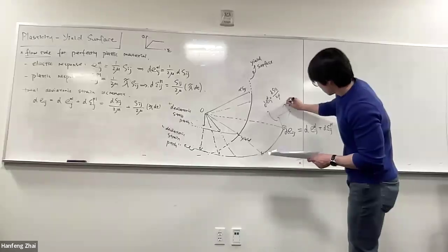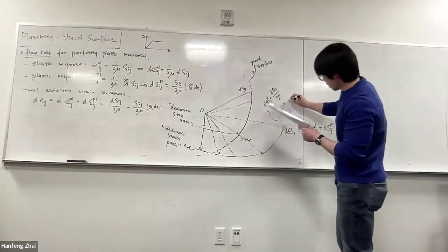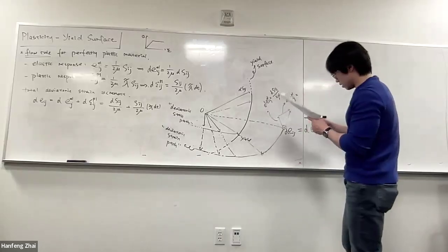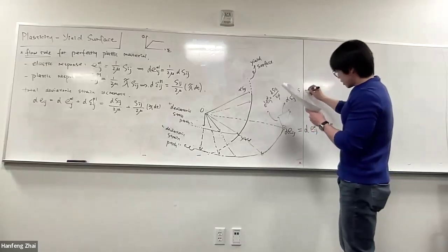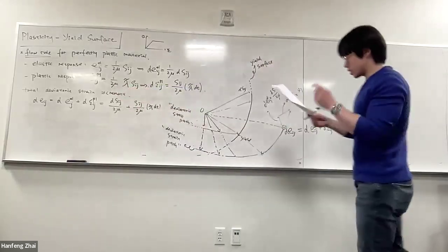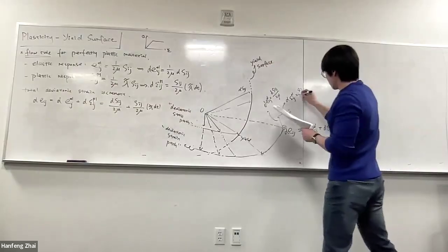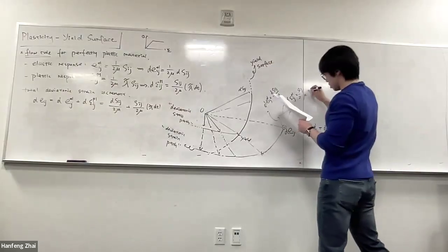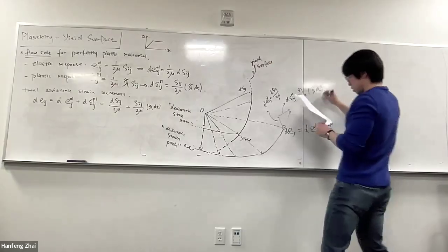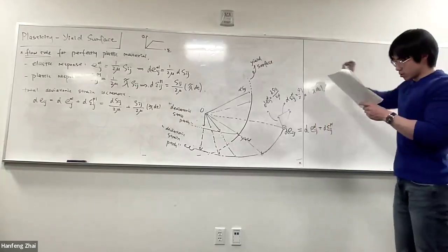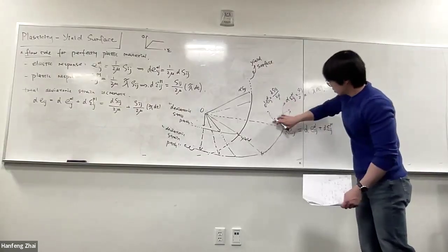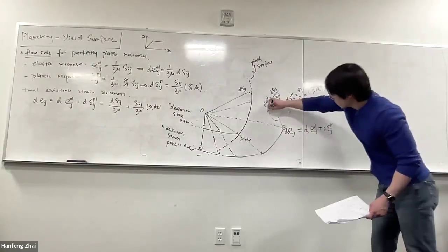And this part would be the epsilon_ij plastic, which is S_ij. And since we start with the plastic strain rate, right? So it's S_ij over 2 mu, shear modulus, lambda dt, which is making a time increment. So this is vector algebra.